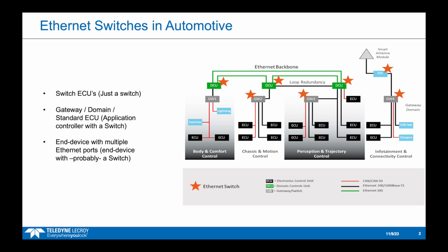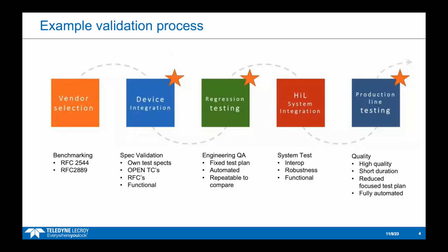Also, an ECU with an Ethernet interface can be tested, so we can do a loopback test, for example against the ECU, or even some bit error rate testing or PRBS, and to test the PHY and functionality of a single Ethernet port. Okay, so here is an overview of the 5 challenges or phases of testing that we're going to examine in this video.